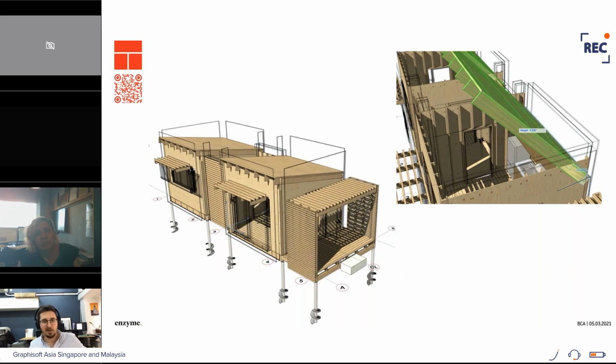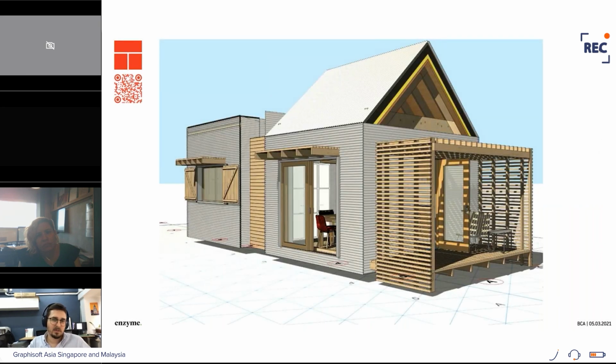How does this translate directly into Archicad? We're working with GDL components that have been designed specifically for these offsite manufactured elements. These GDL components give us the specific sizes and the specific things that will come from the factory, and with only a few of these objects, we can produce almost all the design inside Archicad, also making the design process very efficient.